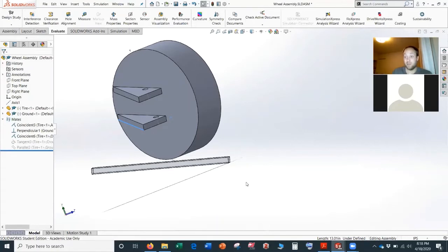On the left tire, because it's naturally coming off the ground, it's going to allow the spring to stretch out basically. And so what that does is it's going to shift weight from the front left to the front right. If you can imagine that, which is great because you're making maybe a hard right-hand turn, and all that weight shift is coming to the front left, and you want to unload that, give some back to the front right, and it's counteracting some of the roll. So this is great. This is maybe even more beneficial than the kingpin inclination in a turn, right? Because you're actually giving yourself the desired weight shift that you'd want to give you better handling.